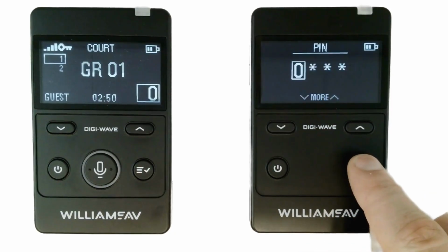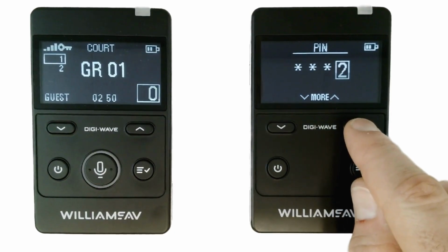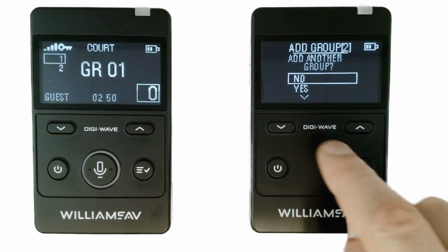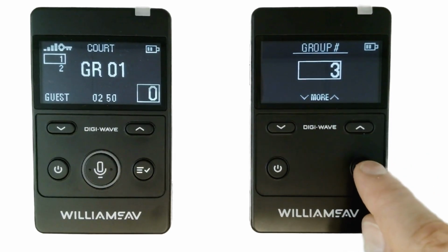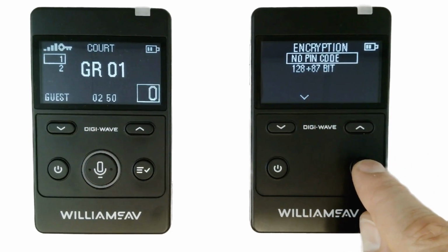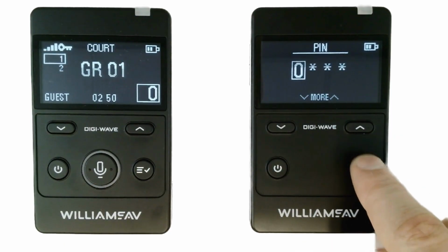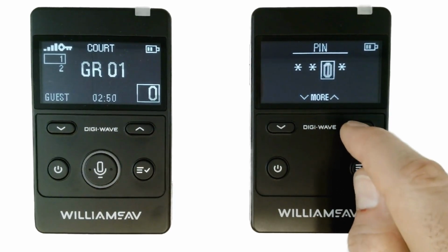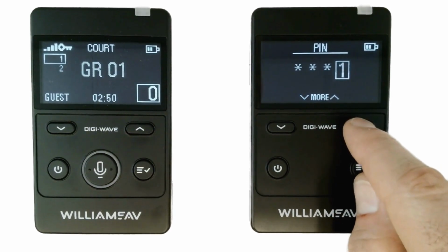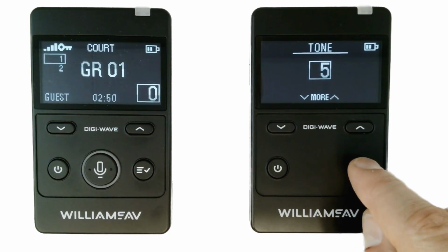If the receiver needs to be configured for more than one group, you can follow the same steps as the guest DLT, understanding that some basic device-specific functions on receivers are different from the transceivers, and receivers don't have advanced settings, but some advanced options for transceivers are actually basic options for the receivers, such as tone, line-out gain, auto-off, and sleep mode. In the next section, we'll test communication to ensure that everything is working properly.